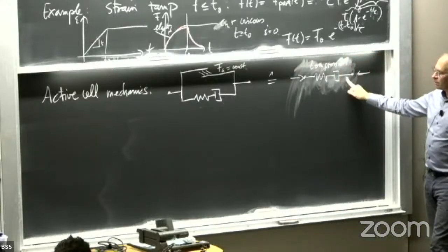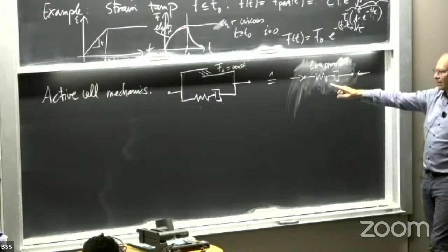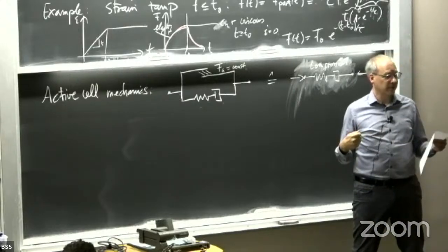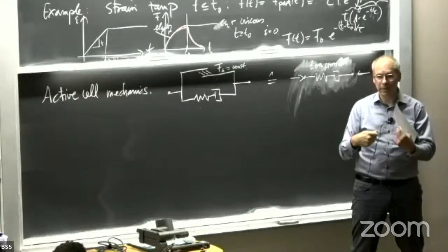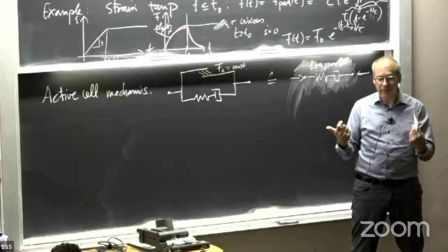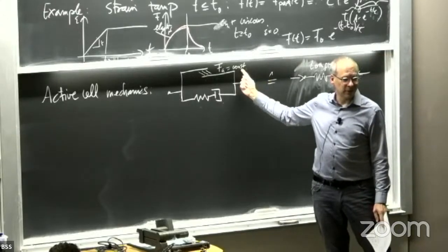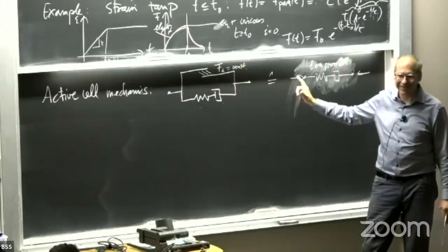Now you see the problem with this is that this is not really stable. Because we just discussed what happens in a Maxwell element. You can pull out infinitely large amounts of material. If you compress, you can push in infinitely large amounts of material. Okay? And the motor is pushing all the time with a constant force. So this model is nonsensical in a certain sense, okay?